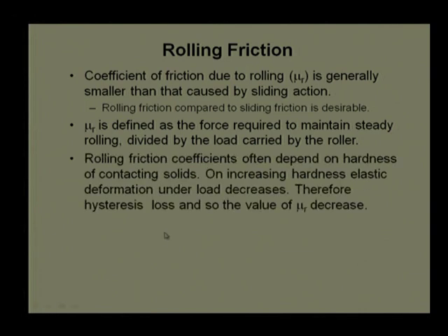One of the interesting things is that the rolling friction coefficient depends on the hardness. So, there is a symmetry, a similar behavior. Sliding friction also depends on hardness. By and large, the higher the hardness, the lower the coefficient of friction. The same behavior is adopted by the rolling coefficient of friction also. The higher the hardness, the lesser the coefficient of friction. The reason behind this is that if there is high hardness, the magnitude of deformation will obviously be lesser, and the depth of penetration will be lesser in that case.